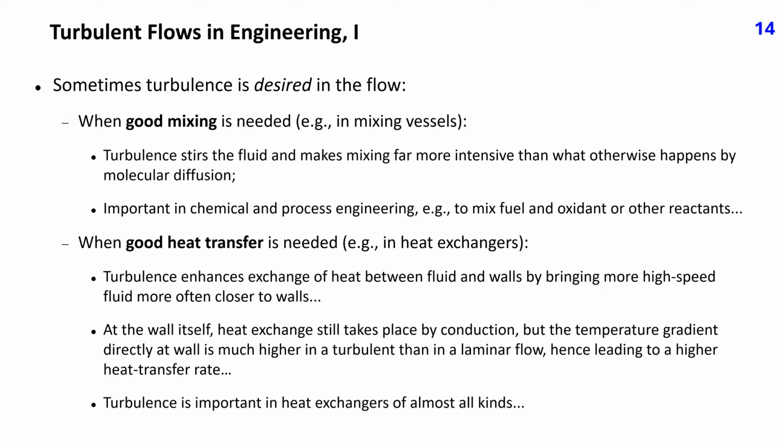When good heat transfer is needed, for example in heat exchangers, because turbulence enhances the exchange of heat between fluid and walls. Turbulence moves fluid parcels across the flow and thus brings high-speed fluid more often closer to walls, where they can pick up heat and transfer it away from the wall.